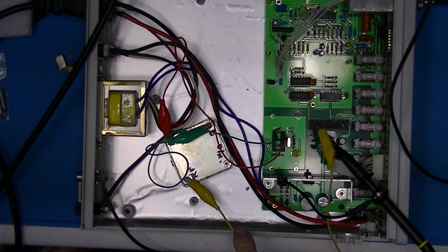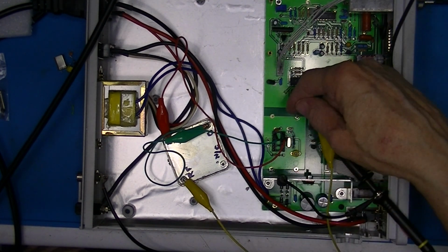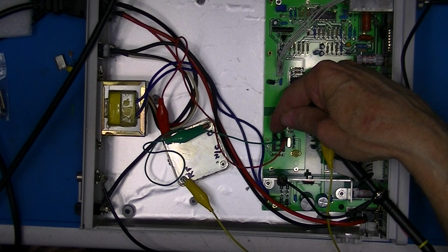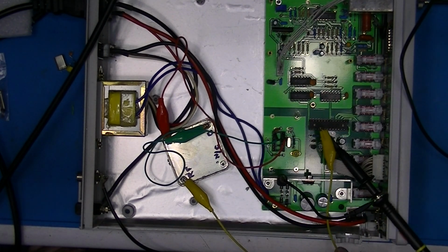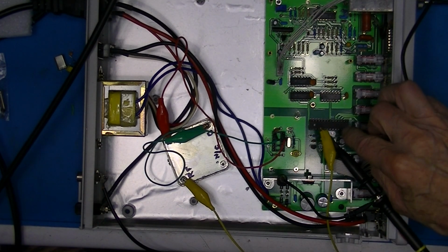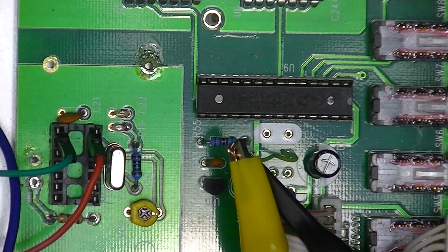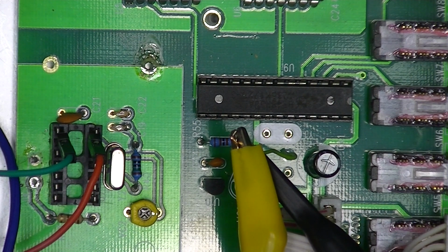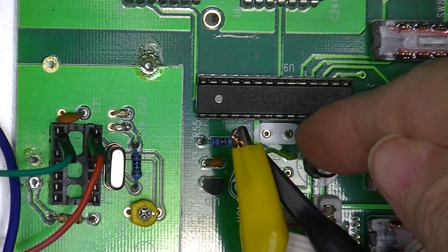This doesn't look pretty, but here's a TCXO. It's getting 5 volts through this red lead. Chassis ground is carried over on this green lead. And this yellow clip carries back, and it's not pin 21, but it's pin 22. These leads out of the way. You can see I've removed the components. I've attached this wire to pin 22.